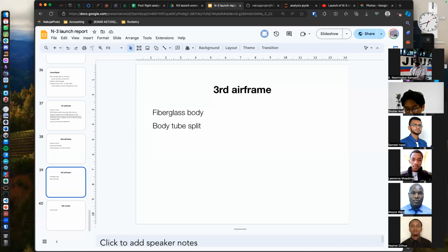So the likelihood is that, one, it will deflect the thrust and the flight path of the rocket. Two, the micro pocket of high pressure will affect the burning characteristics of the fuel, and that will create a situation whereby the motor cannot balance the pressure. So the likelihood is that it will explode, as you witnessed. So the two likely scenarios have been computed because of the proximity of the nozzle ejection to the plate, for those reasons.